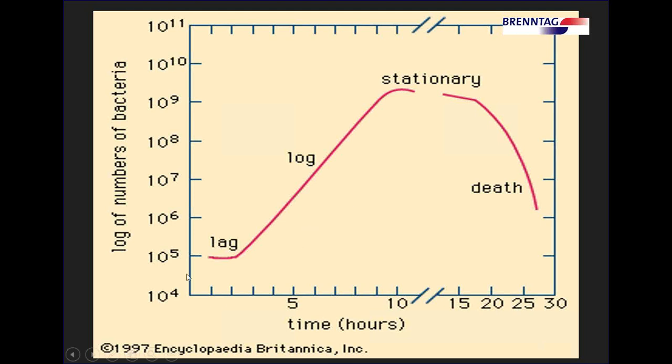If you look at this logarithmic scale of growth, and you look at the bottom, you see a time scale, and at about 5 to 10 hours, it's a done deal, folks. So if you sit there and aerate a waste that's already treated for much longer than 10, 15, 20 hours, you're probably doing yourself a lot of damage, which we'll talk about in just a little while.